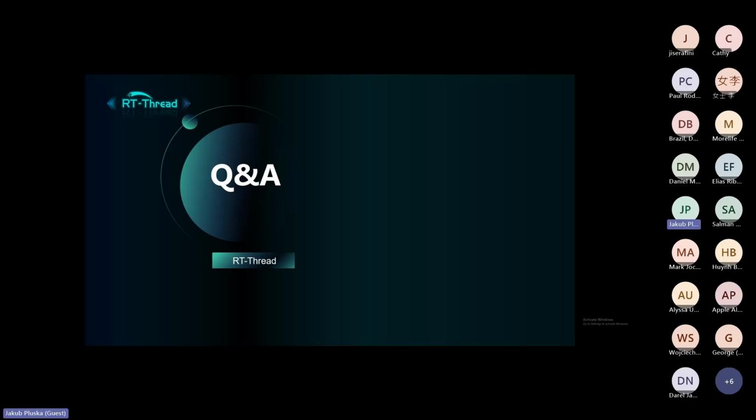Paul, regarding the PLA, I would say it depends on the printer you have, because there might be a printer which is open like mine, or a printer which is closed. So there are different ones. I can see that Devil Design suggests a hot end from 200 to 235 Celsius degrees, and a heated bed from 50 to 60 Celsius.